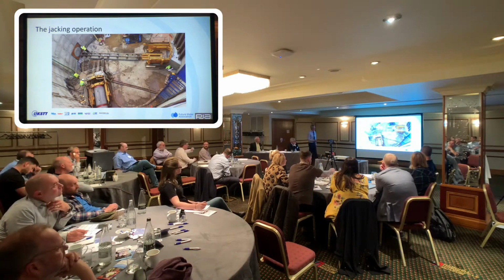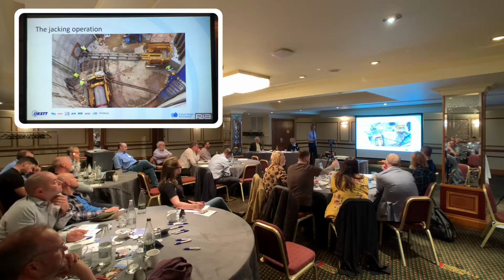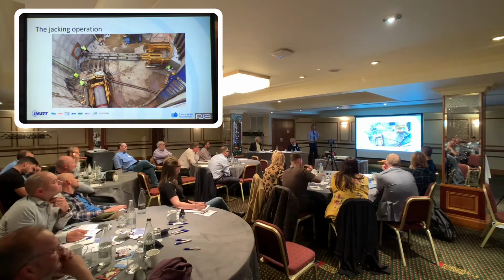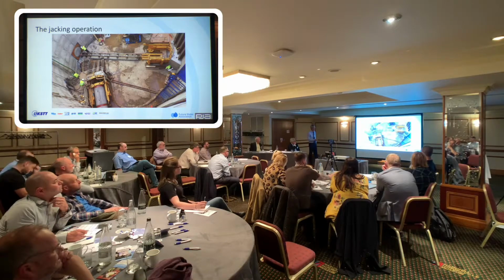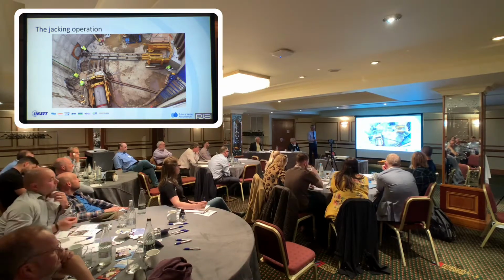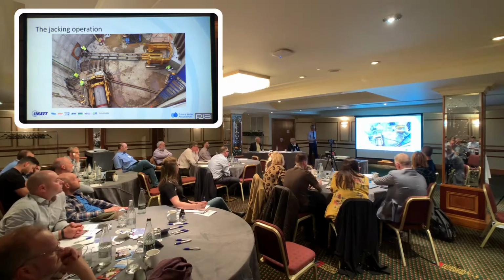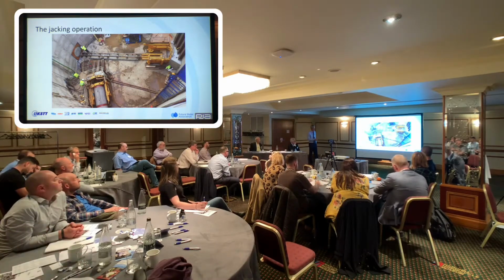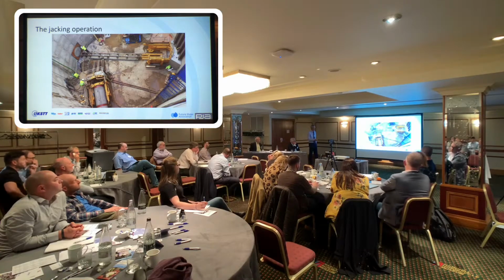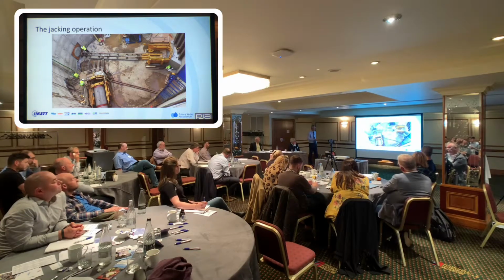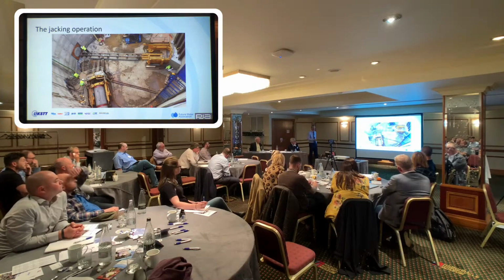So this is a picture of an interesting project in London, where a new pumping station has two incoming feeds from very different directions. So we've got one microtunnel being set up here with a back wall there, and one microtunnel being set up here with a raked A-frame to take the load into the base plug to be driven here. Now, both of these drives were installed simultaneously.